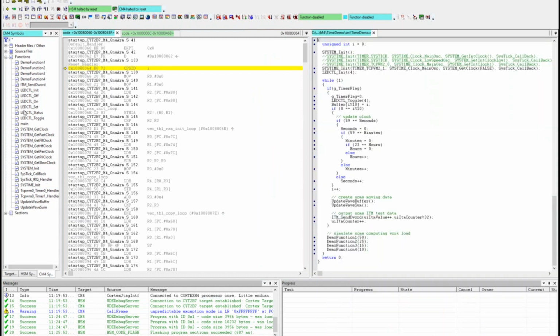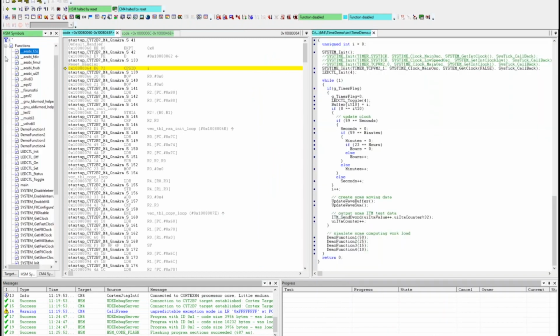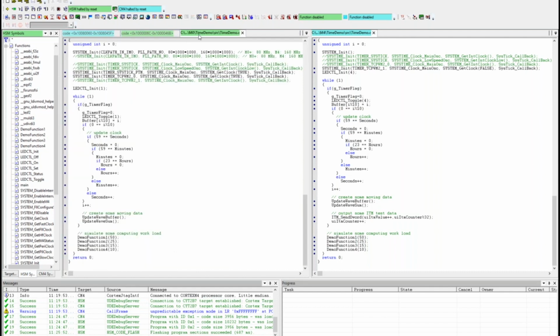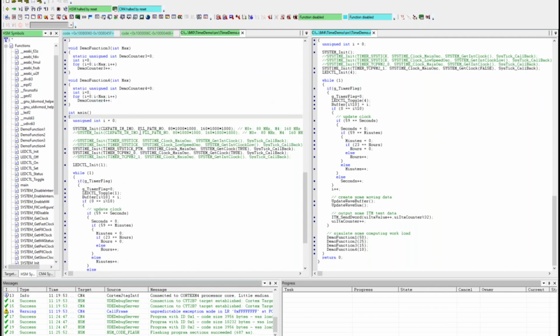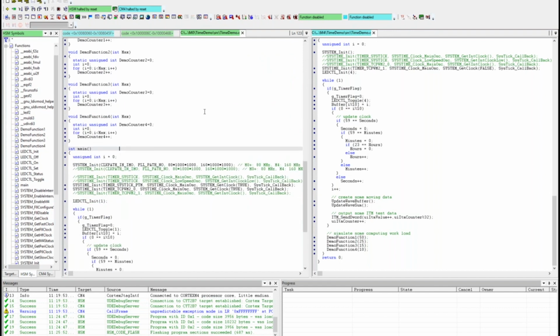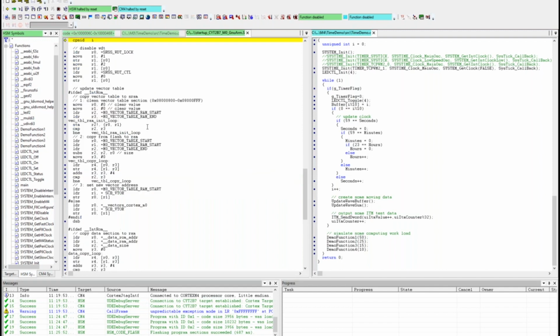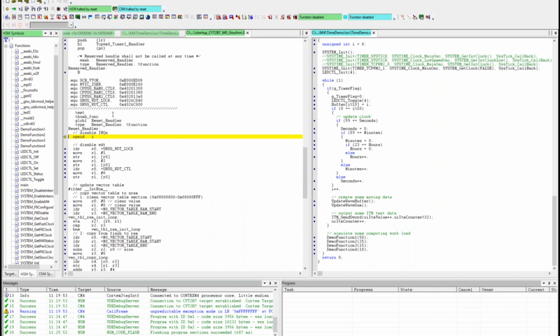I put it on the right side, and then also for the HSM I can open the folder, the file, and then I can look and now start debugging. There is something specific that may happen in such a configuration. If you look at the position of our program counter after reset, we see here that it is not the start address of our application. It is somewhere in the reset handler.